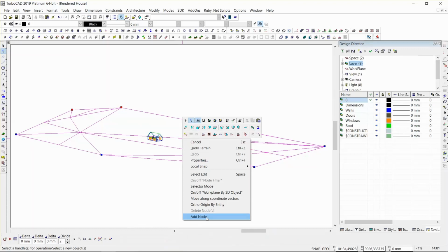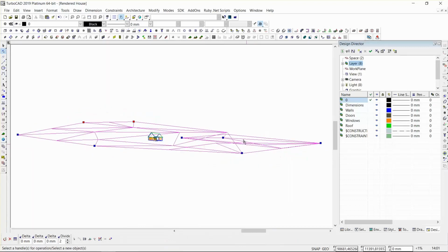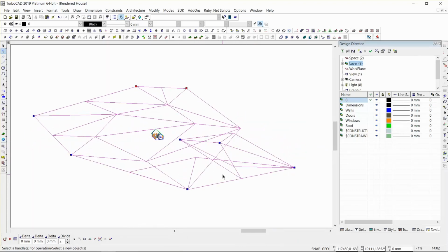Add node, I think this is probably gonna... and we can move some nodes like that. Alright, so you can add a bunch of different nodes, and then you can select, let's say, these two, and I can change delta, should be this one. And then you can change the height of those nodes. It's just going to put it straight up, but if you need a lot of them, you gradually change them to get to a certain terrain. Then you put a flat view on it, and then you can measure it. Yes. Okay. I just can't even think what height we should go here.